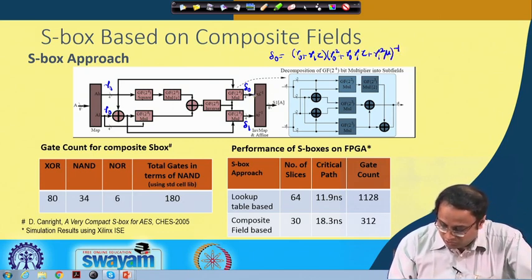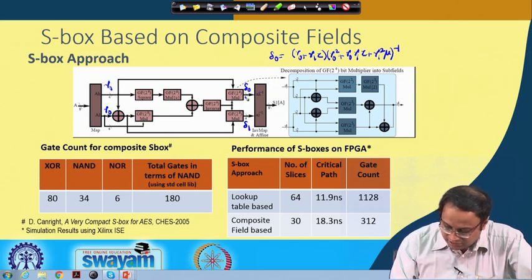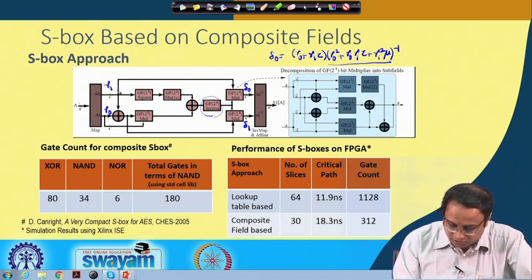You can note that this is exactly this part here, the GF(2^4) inverse which is being computed. So the input to this inverse: you have gamma 1 as this input, you do a squaring, so this becomes gamma 1 squared, and then you do a multiplication with a constant, which is mu. So you calculate gamma 1 squared mu here.